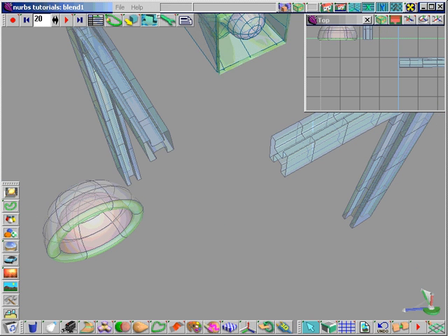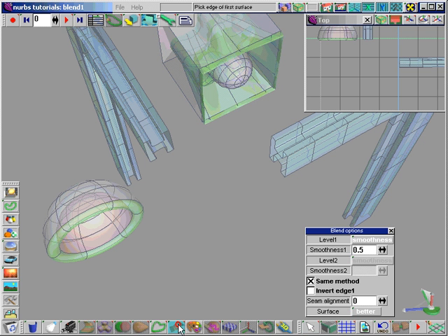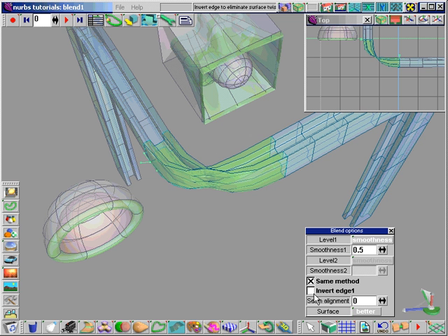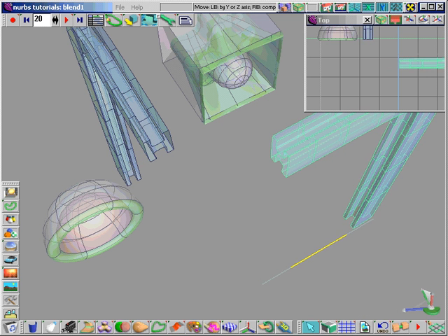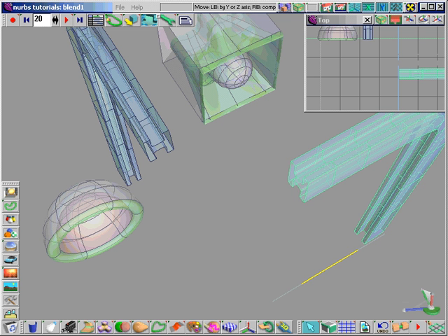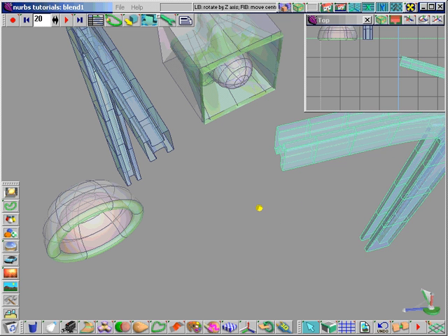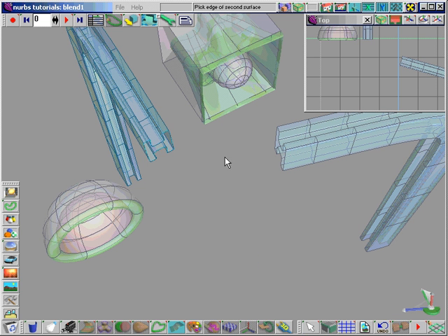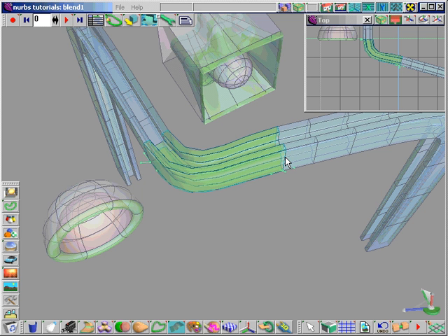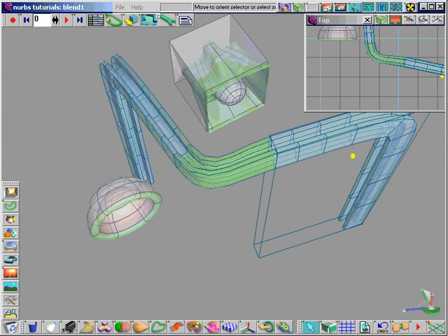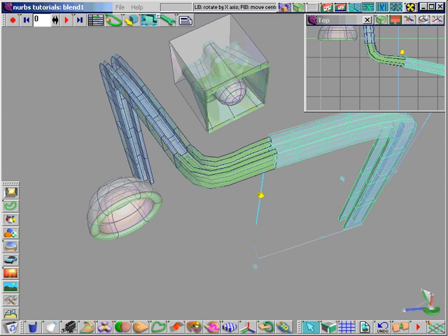Blending at acute angles can yield unusual results. It's best to blend at wider angles and then rotate part of the geometry. Here we have a couple objects at roughly a right angle to each other, and the resulting blend appears to be twisted. Using the Invert Edge and simpler Better options isn't solving the problem. So let's back off and rotate one side so that it's at a more obtuse angle to the other. Now the blend is much cleaner, and we can reposition the pieces to achieve a much tighter radius and smaller angle.